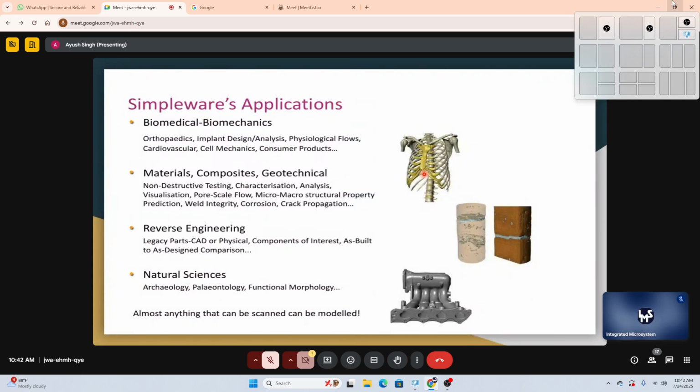Now, coming back to the other points that are covered, the reverse engineering part. So, if we have any CAD object that we have designed in SolidWorks or any other modeling software, what we can do is reverse engineering. We can scan the data set, put it as input in Simpleware, and later on use the surface deviation feature to check the accuracy of the printed model versus the design part. So ultimately, we can increase the efficiency of doing any sort of CAD modeling.